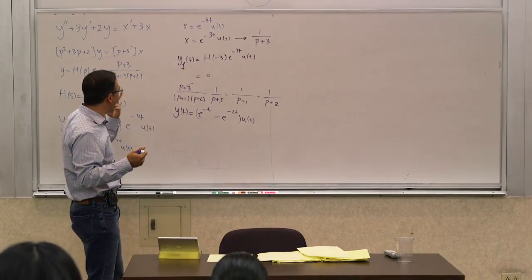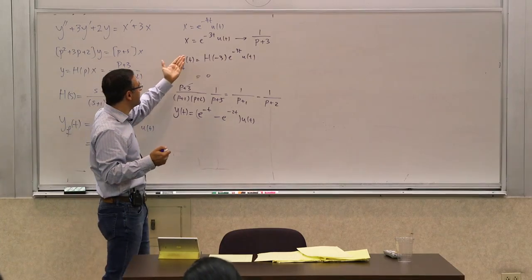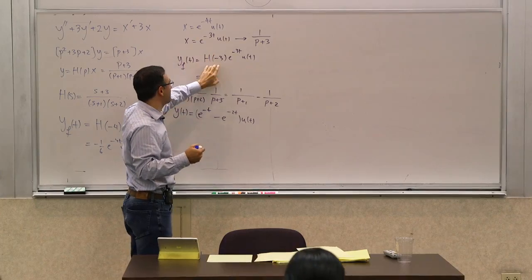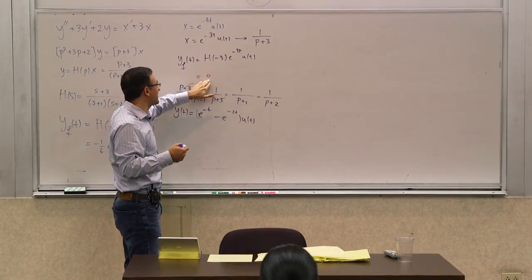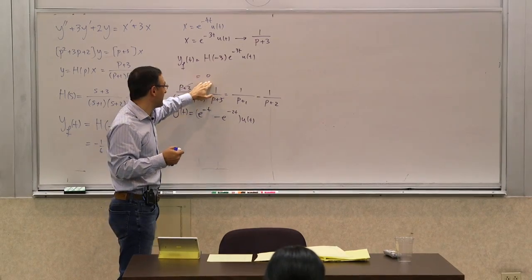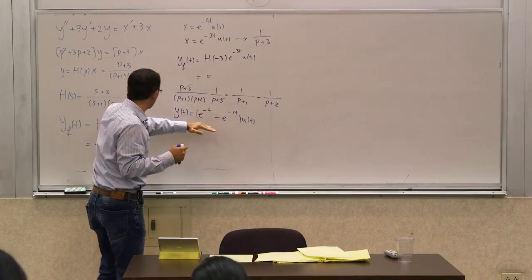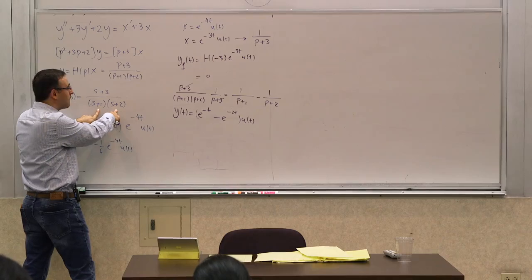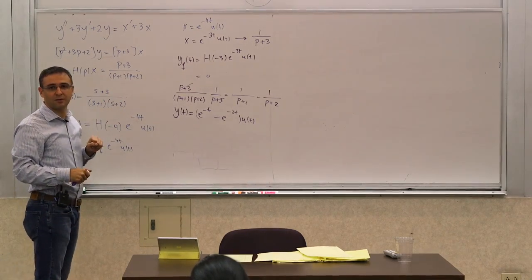The insight is that you had a system, you hit it with e to the negative 3t, but because this was a special frequency for this system, it was one of its zeros, it did not produce any forced response at that frequency. It didn't mean it doesn't have any response. It does have its natural response. You see both of its natural frequencies, but you don't see that particular input frequency.